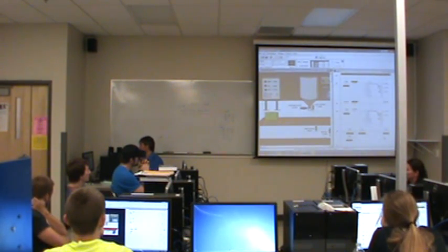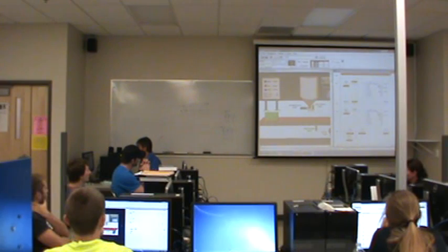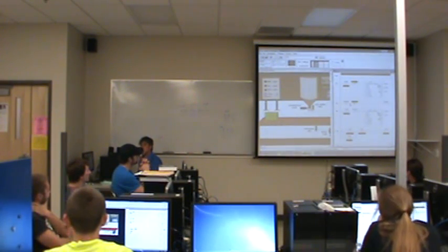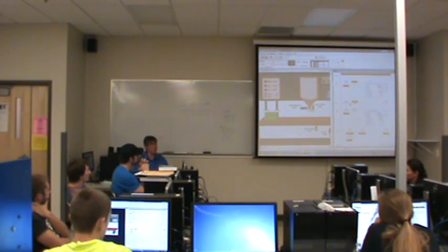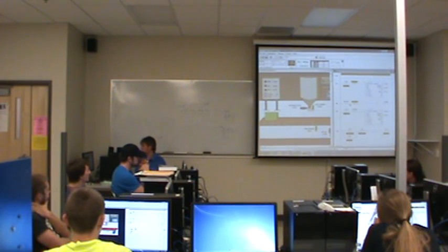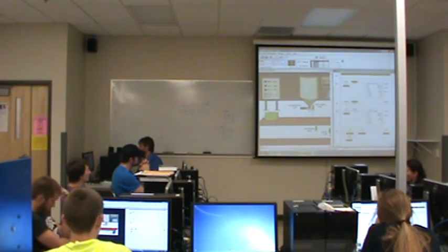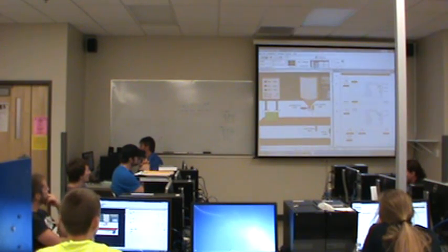So the address is a little different, which means that I also need to change these. Does that make sense? This is a different simulator, so I've got to change where some of the input and output addresses are located. Now my start and stop button should work and should start and stop the cycle. Okay, I'm going to get rid of this whole run, because that's no longer the sequence I'm interested in.